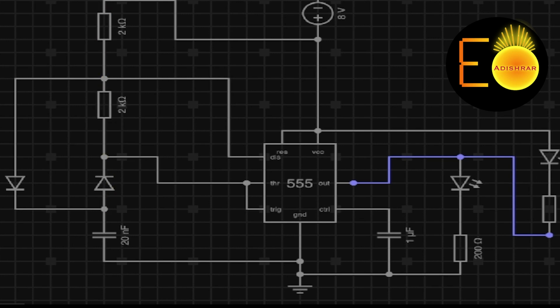And during the discharging operation, when the capacitor discharges, the current will flow through the diode, the resistor, and this discharge pin, because when the capacitor reaches 2/3 of VCC, this discharge pin will be shorted to the ground, and it will find the lowest resistive path through the discharge pin.